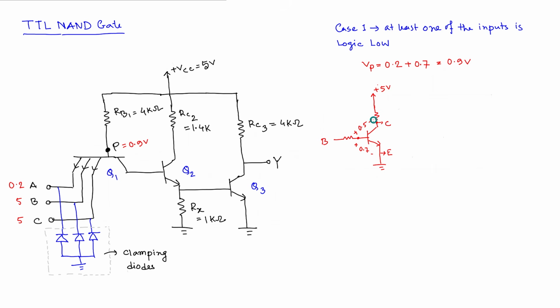This is partially true, not wrong, but you see here, in this case, we are looking at a condition whenever we want this particular junction to be forward biased, right? So in the next case, we will see that whenever we find this particular junction to be forward biased, the voltage we will require will be 0.7, okay, not 0.5. And we will also see that at that moment this particular junction is not forward biased, so we call that situation reverse active mode.